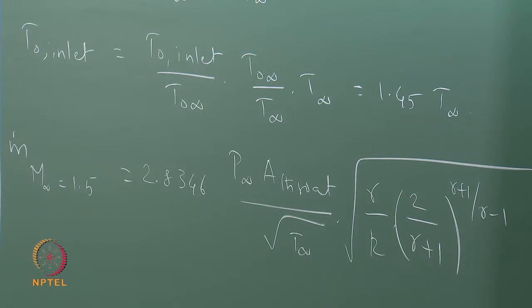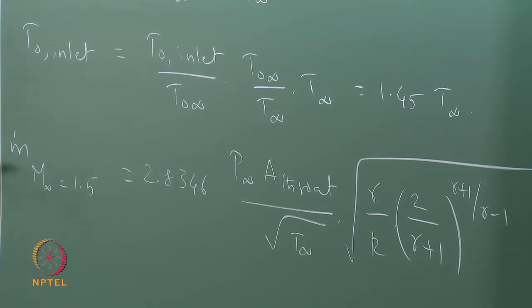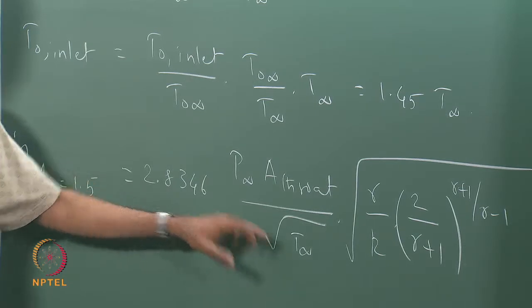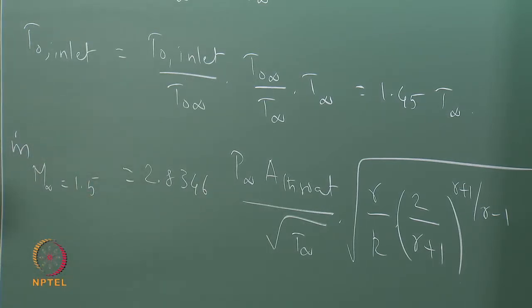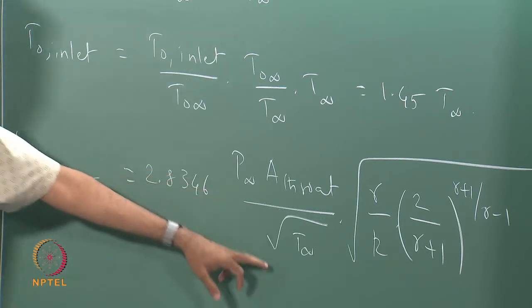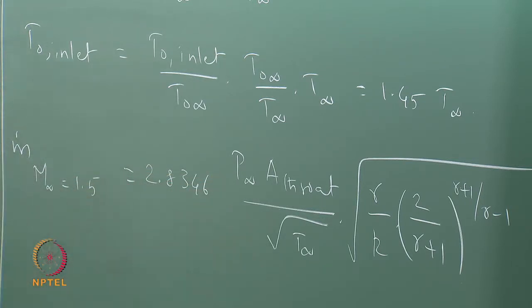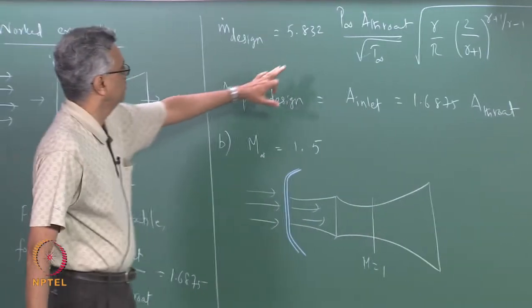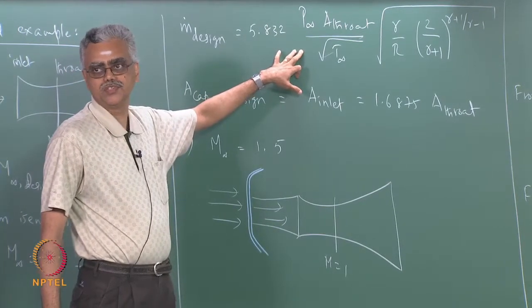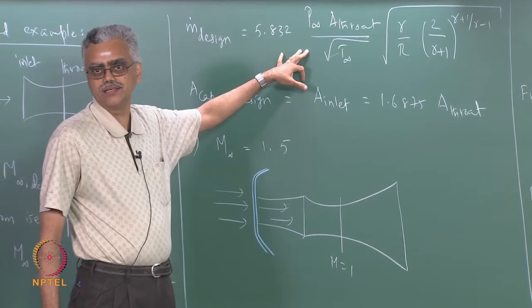It now becomes clear why we wrote everything in terms of the free stream static quantities, because although the Mach number has reduced, the free stream static pressure and free stream static temperature remain the same. We are only looking at a reduced speed for the intake, which is why we wrote everything in terms of P infinity or static conditions here and also in terms of static conditions here. So, we are assuming that static condition remains the same, I have only reduced the speed of the intake.